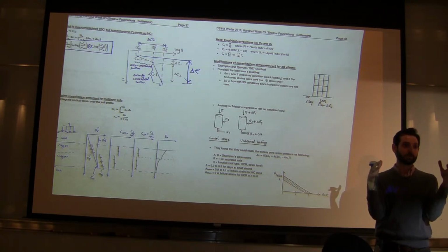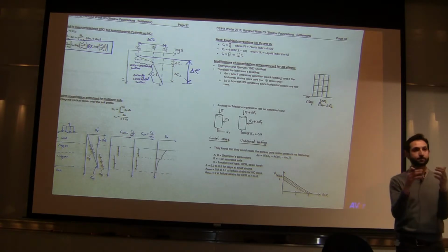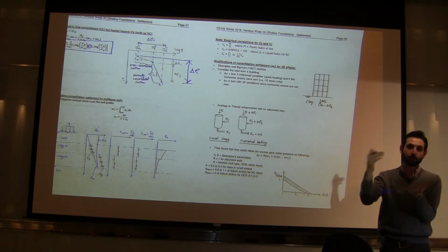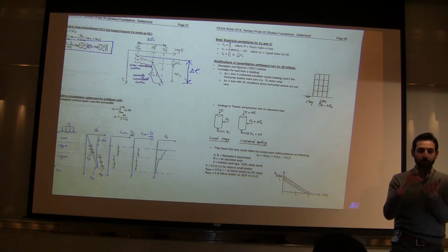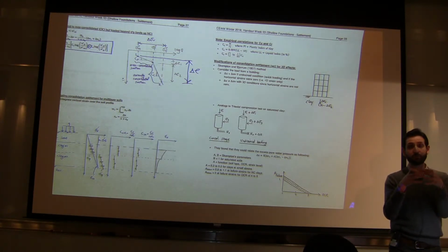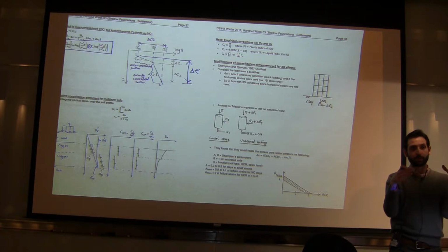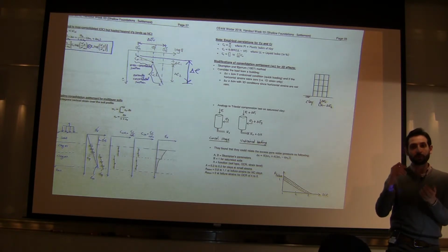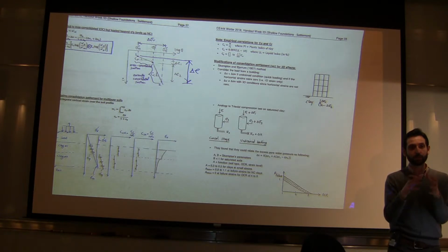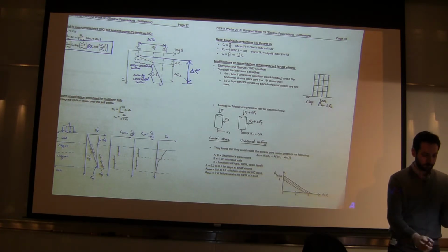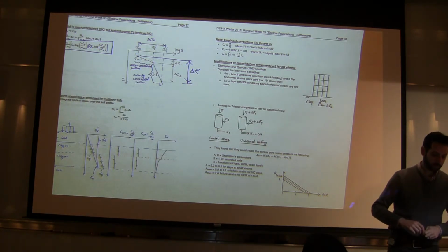It cannot expand. Now going back to that spring analogy, you apply a load, first it goes on the water, and then the soil starts to shrink and load transfers from the water to the soil. Now imagine a case where that rigid ring is not rigid anymore. It's a flexible ring, so as it consolidates, it can also expand a little. Would you expect the pore water pressure dissipation to be the same as in the rigid ring? Probably not, and that's what drives this last piece of the consolidation settlement that we're going to talk about.